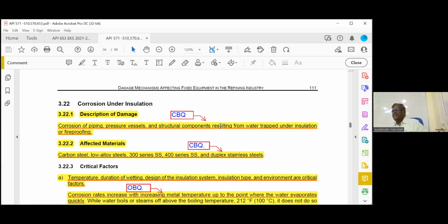But how will you check? Remove the insulation and check. Without removing insulation, there are also other NDT techniques. Deep penetrating eddy current. You might not have heard of this one. With deep penetrating eddy current, we can measure the thickness through the insulation. And even nozzles, I told profile radiography. Without removing insulation, we can also measure.